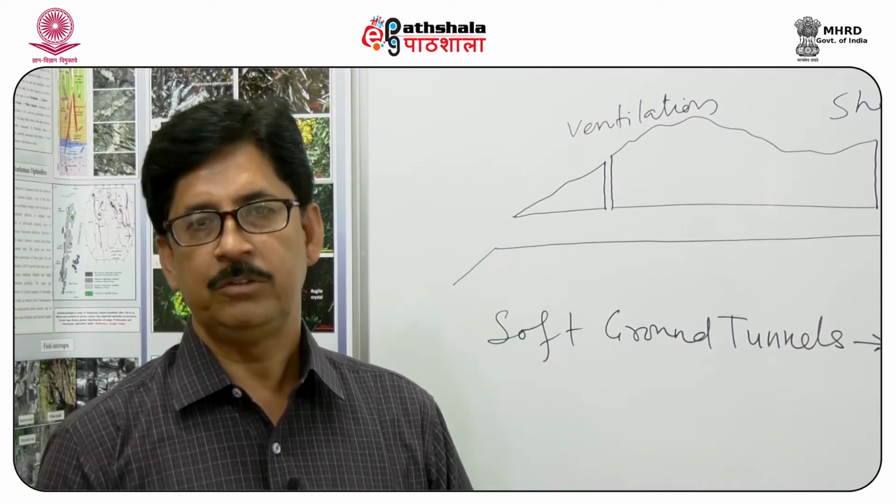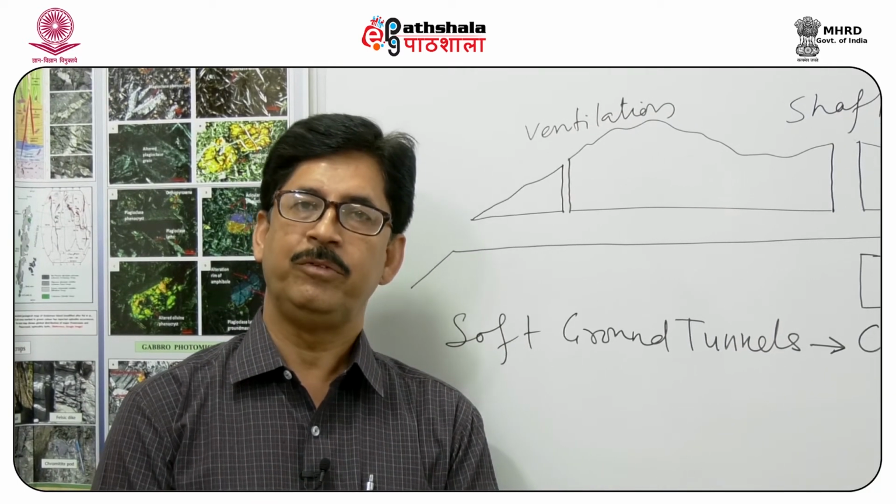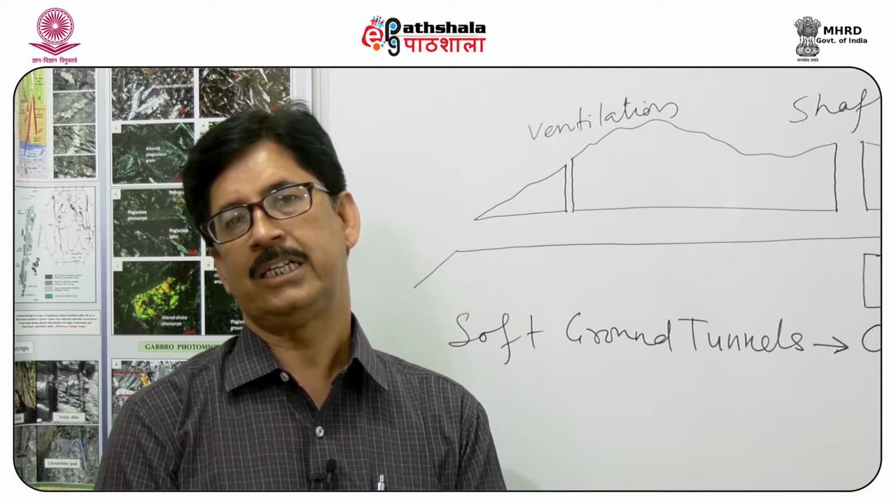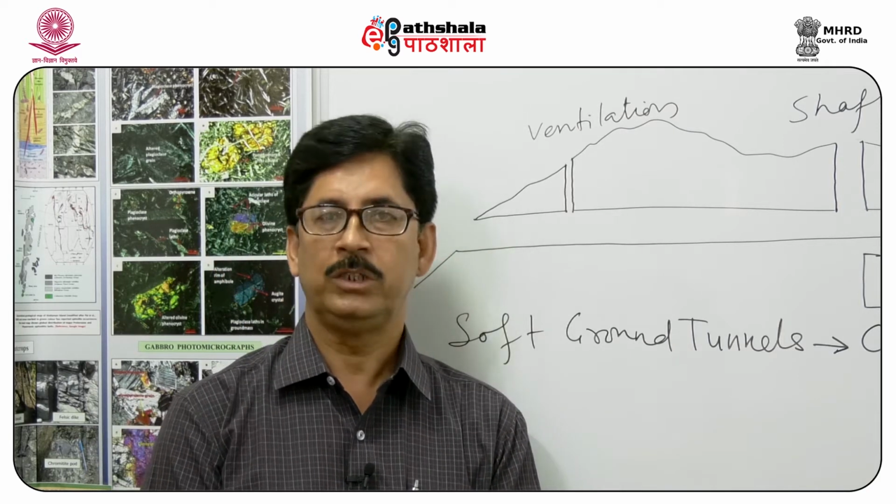And then the earth which we have excavated out can be filled back over the roof of the tunnel. So this is called the cut and cover method, which is used for soft ground tunneling.